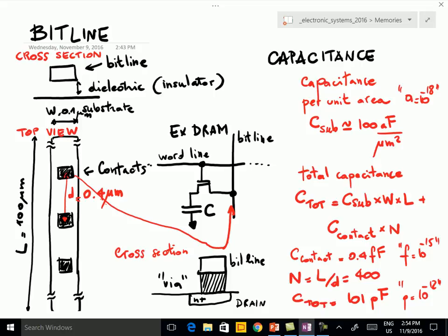Why is this important? I want to stress the fact that each cell, which contains one bit, is connected with a much larger capacitance. And this is something critical in the operation of the DRAM, because, as we will see in a moment, it is the reason why for a DRAM we need the continuous refresh of the information. This is something we also need for SRAM. For SRAM we do not need actually continuous refresh, but we need to refresh the information when we read it.